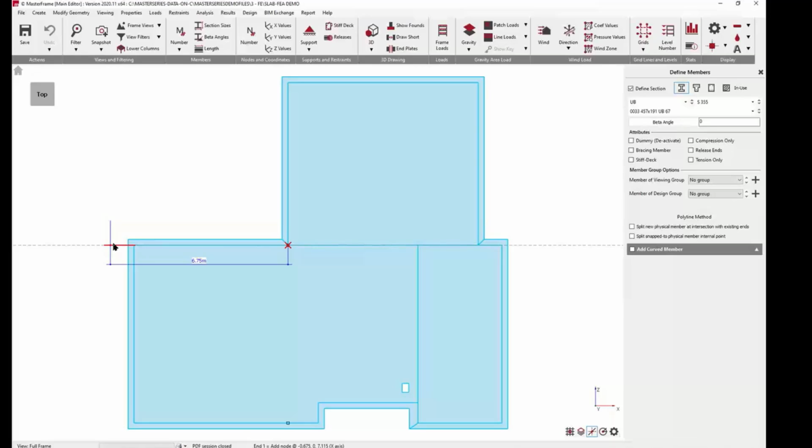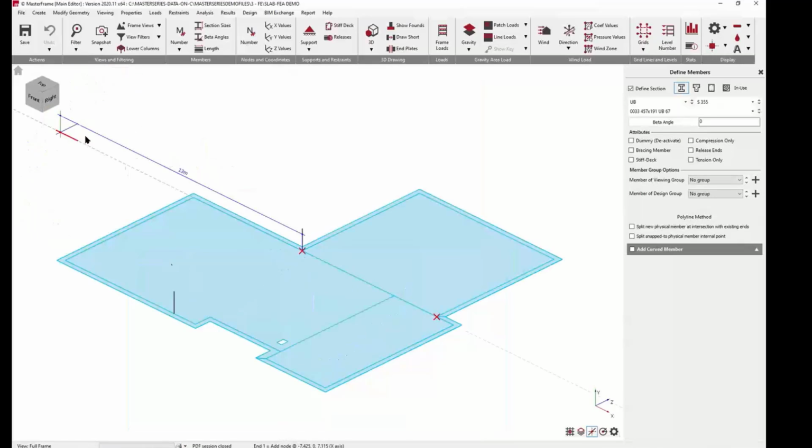It does give you a slight advantage, but it's not necessarily necessary to have two sets of lines and everything. We've also got a major wall coming across here and here. There's a third reason for actually putting these lines across. We could do without them if we had to. And the other interesting thing is that I have introduced two columns. Now, there's 2 point loads coming down, and for punching shear, you really need a column above or below. In our case, a column above. Otherwise, it doesn't know how to handle it.